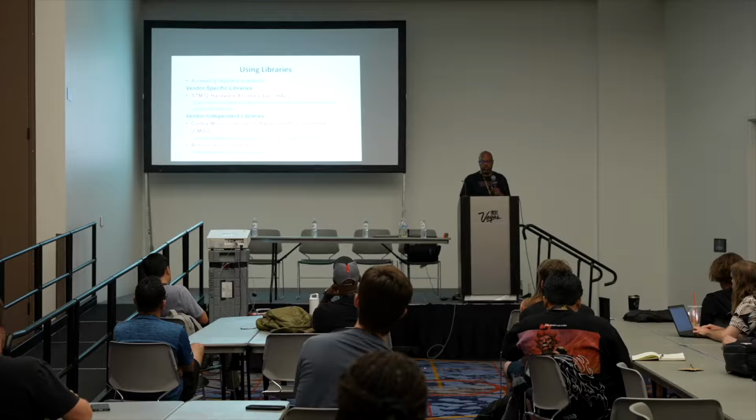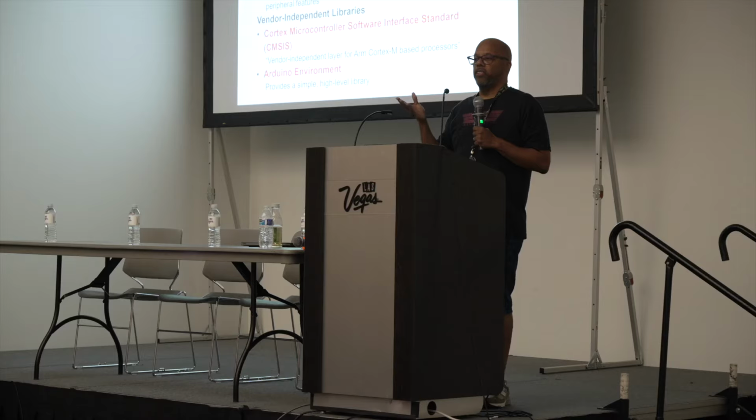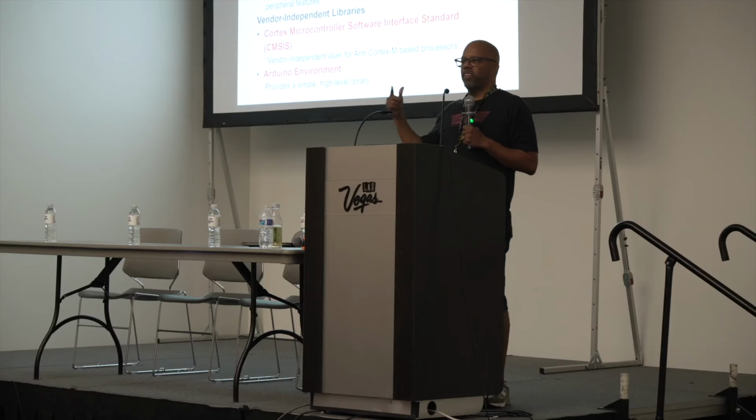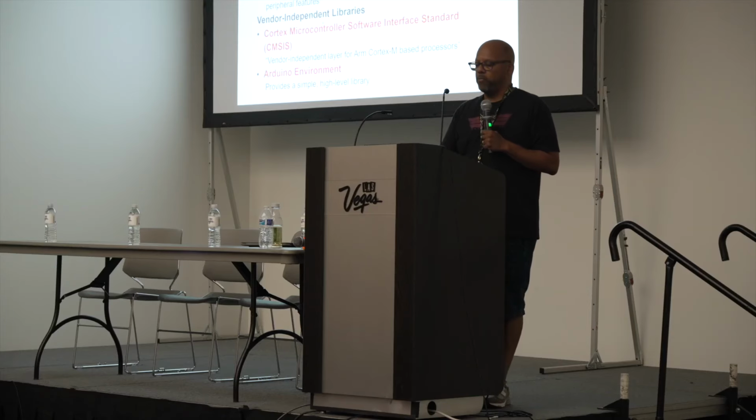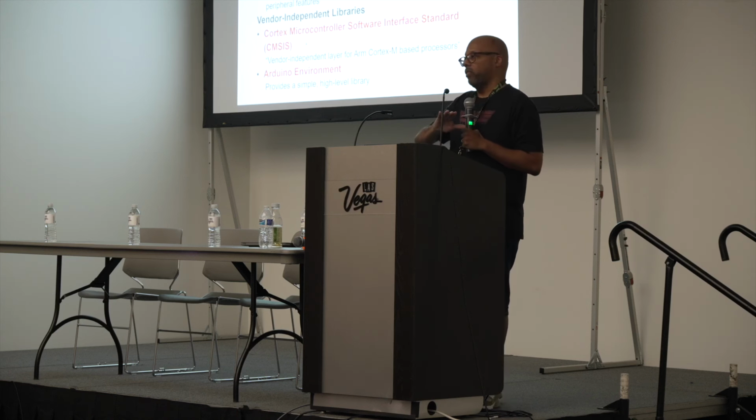So there are vendor-specific libraries, like I'm using this for STMicroelectronics. They have their HAL library, right? STM32 HAL. Then different vendors have their own libraries. Plus, there are vendor-independent libraries, like CMSIS is a popular one. It's across ARM, all ARM platforms, right?